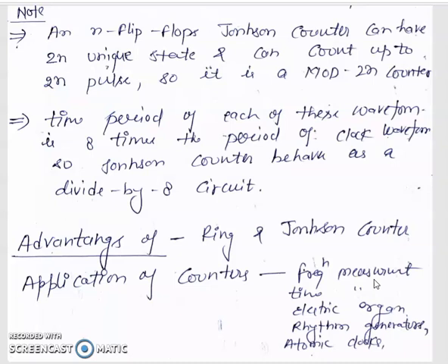In this shift register counter, we have two types, depending on the feedback from the output of the last flip-flop to the input of the first flip-flop. So it counts a number of states either in sequence or not. The first one is the ring counter.